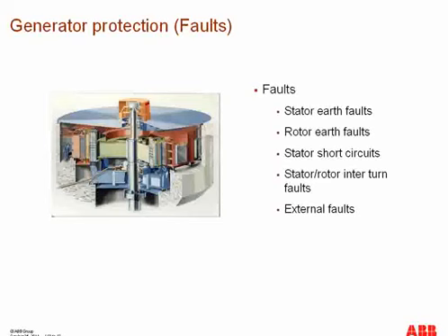But at the same time, we do not want to damage our generator as well. So it's different to the protections provided in other parts of power systems like transformers or line protection, where we just trip and isolate the faulted part of the power system.